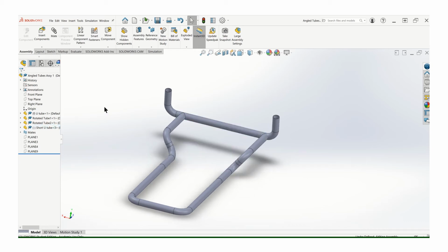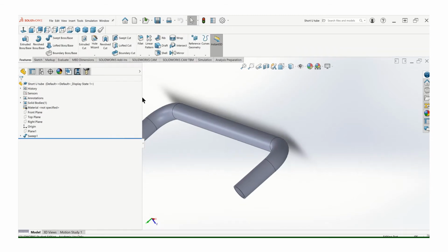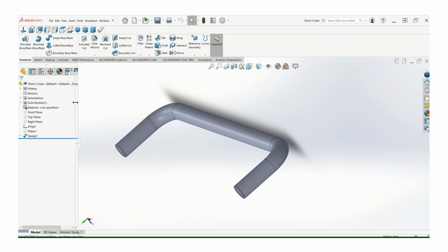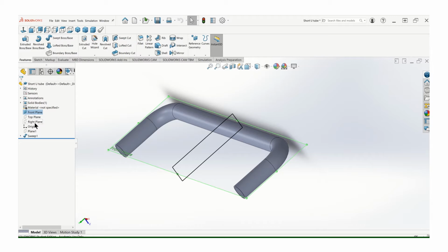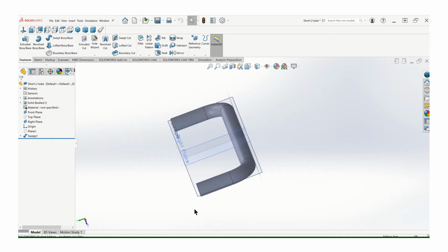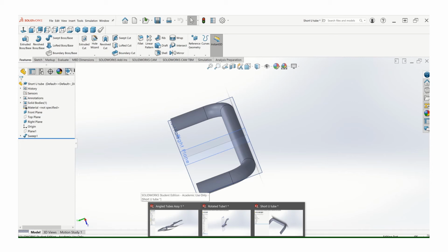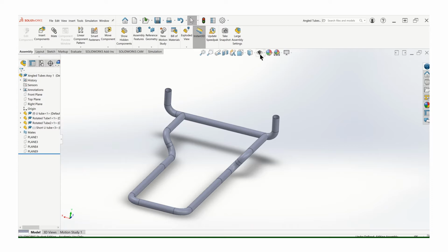So that's where work planes are going to come in. Let's open up this. If you right click, open the part. Now let's turn some planes on here. Let's turn that one on, and then the mid plane one is the one I want. You can see now the method to my madness here. That's why I build my parts around the mid plane, so you always have those as reference points. You don't have to guess about that. Back to our assembly, and there we go.